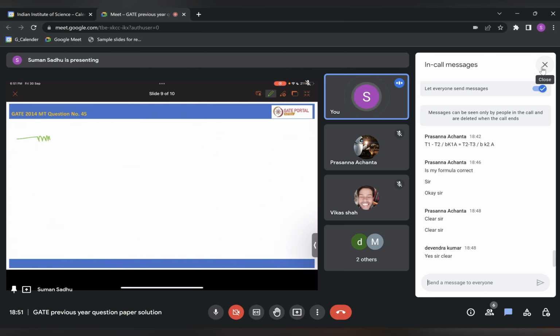Now, as the slabs are connected in series, similarly you can use the analogy of this series circuit and you can find the total Q. What will be the total Q? V equals IR, right? So I will be V by R. What is V here? V is the temperature, T1, T3.